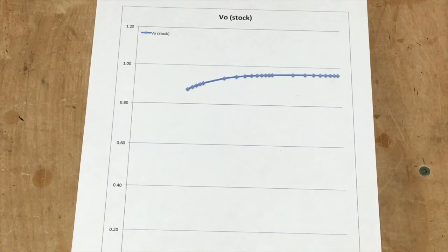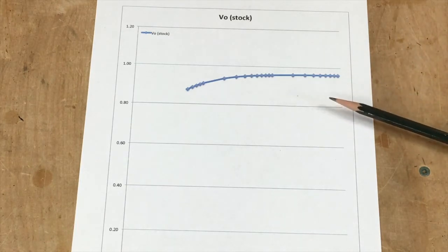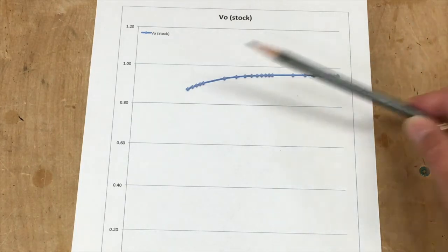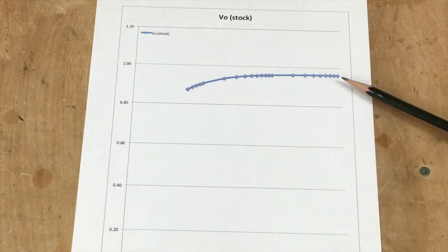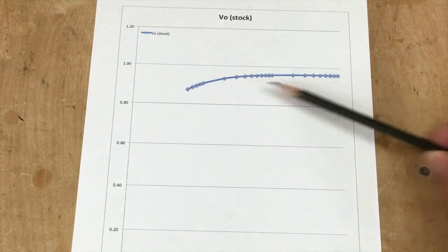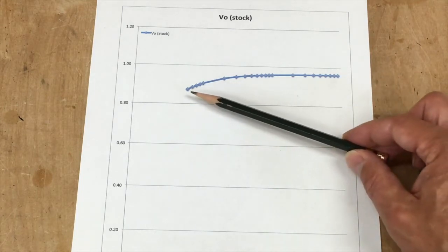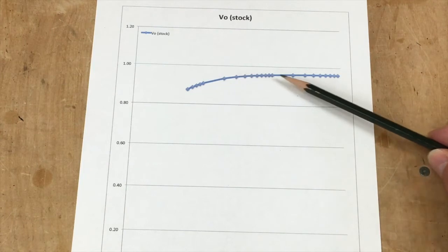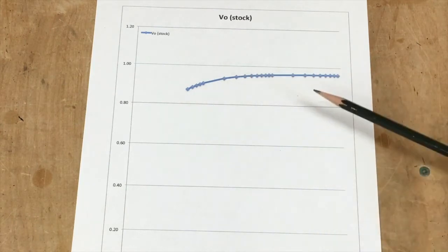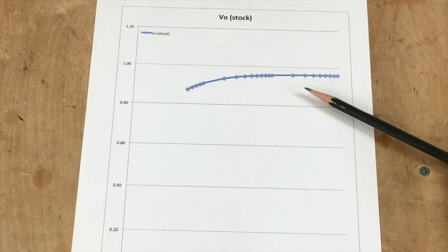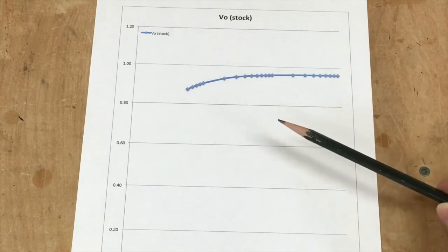So what we have here is I went ahead and put the results of our AC analysis, that equation, into a spreadsheet program and plotted out some values for varying frequency. So this is actually the stock response of that output circuit. This is 60 hertz here, going all the way over to about 10 kilohertz, plotted on a log scale. You can see that the response is kind of down, and then it comes up and kind of levels off. And this is just that one particular circuit. If you were to try and analyze the entire amplifier this way, it'd be pretty complicated. But I'm just concerned about this one circuit.